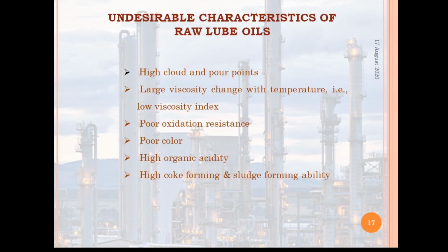So there are some undesirable characteristics for the raw lube oils. These are high cloud and pour points, which are very undesirable. Then a large viscosity change with temperature, that is, a low viscosity index, poor oxidation resistance, poor color, high organic acidity, high coke formation, and sludge forming ability. These are the characteristics which are very undesirable for raw lube oils.